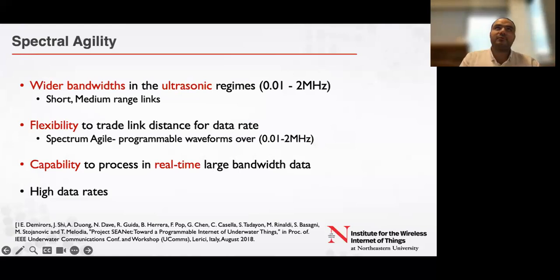For example, for a fast Fourier transform in real time in Wi-Fi devices, you're just looking at a 64-subcarrier FFT. In most of our implementations, when we do OFDM, we have FFT sizes of 8,000 or 16,000 subcarriers. So it is much more demanding compared to standard RF devices because of that imbalance between the sampling rates and the data rates, the bandwidths that we are dealing with.